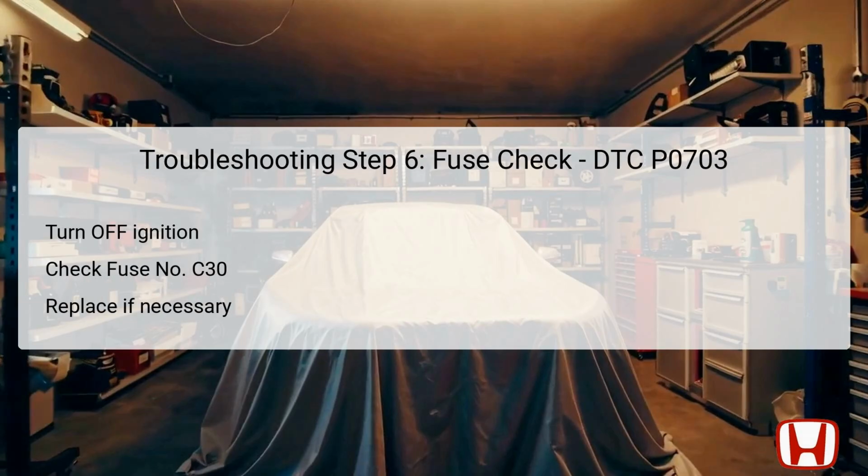In the sixth troubleshooting step, the focus shifts to checking fuse number C30 to ensure it is intact and functioning properly. Start by turning the vehicle's ignition to the off-lock mode for safety. With the vehicle powered down, locate and check fuse number C30, which is integral to the brake pedal position switch operation. This fuse can often be a simple yet critical point of failure.